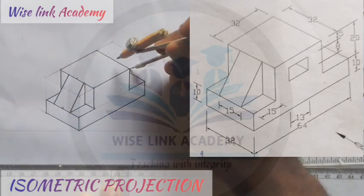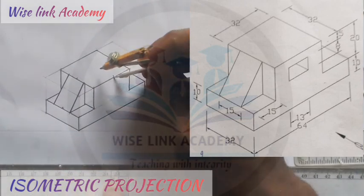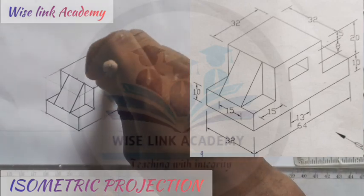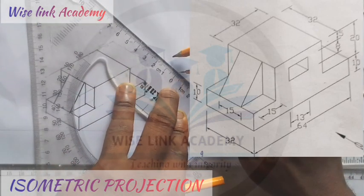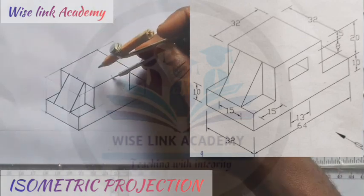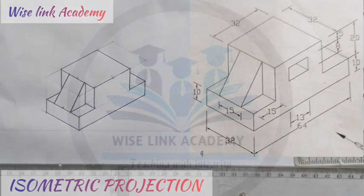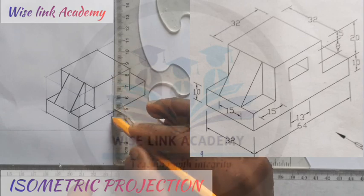So at this point, take it to measure 16, my center. Measuring out 16, I'll take my meter rule. 16 is 0, 15, 16 at this point. So at this point here, I'll take it. As you can see, it ends at this point. So this is 16, this center here. With the help of my set square, that center, I'll draw it down with a faint line this way.